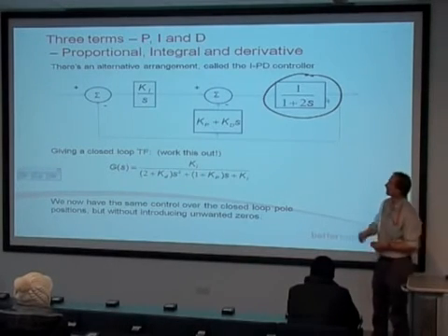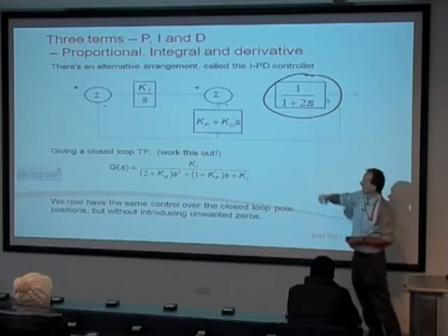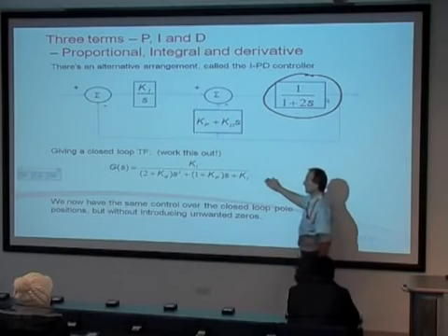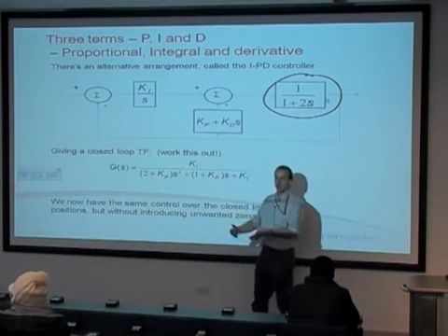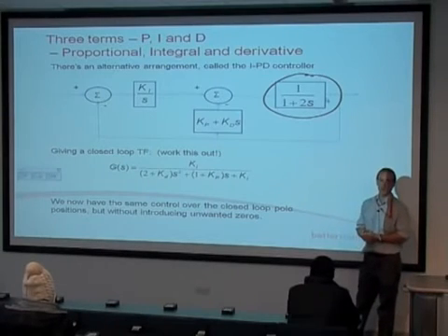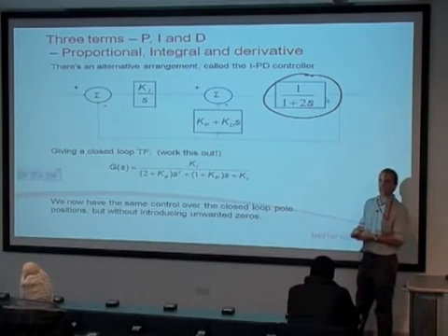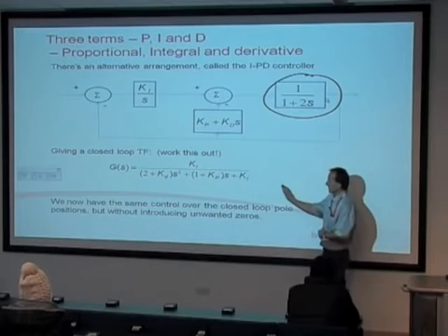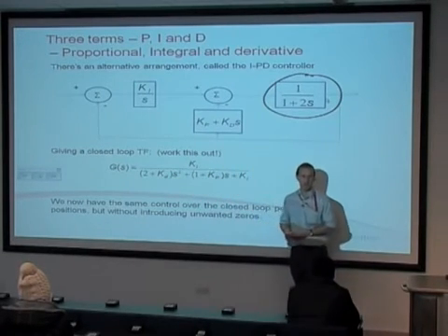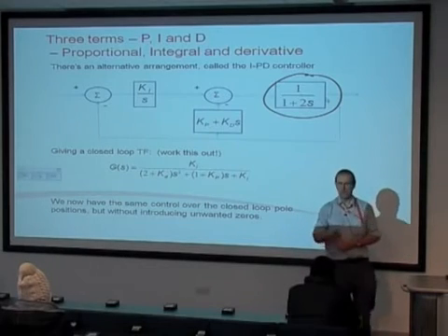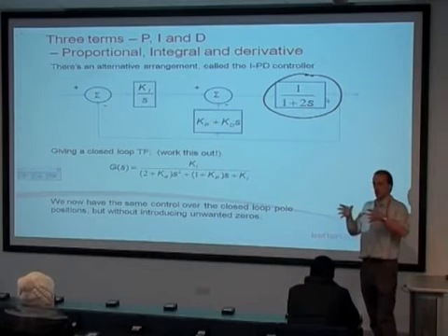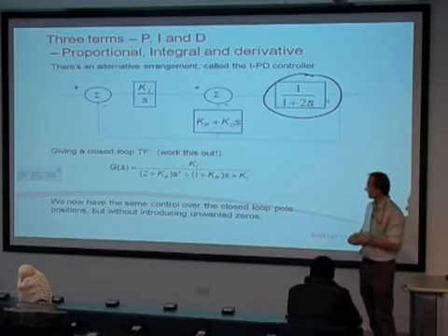No. Because if I've got S cubed up there and an integrator, I'm going to end up with a denominator here that's going to be probably fourth order. Again, if you plow through the block diagram simplification, you'll see that will come out as a much higher order equation. Okay, so I'm going to have a high order denominator, still with a whole bunch of variables in it. And this is where you start to find that having the three variables is helpful when you move up from the second order system.